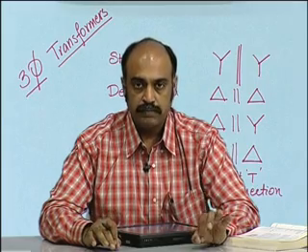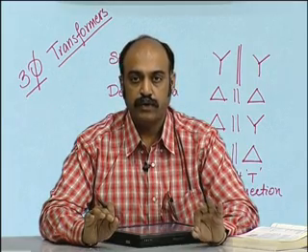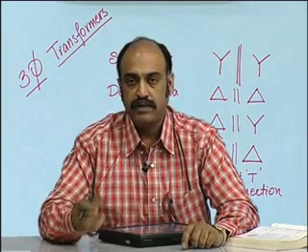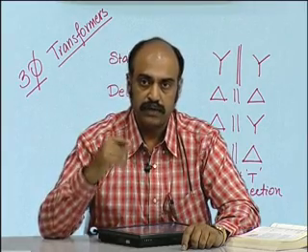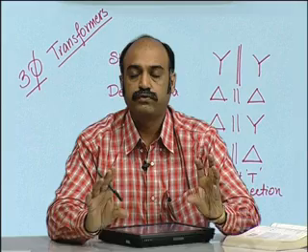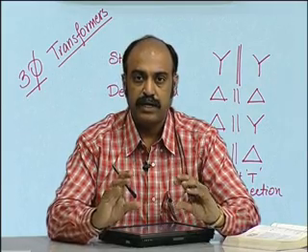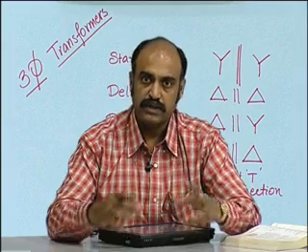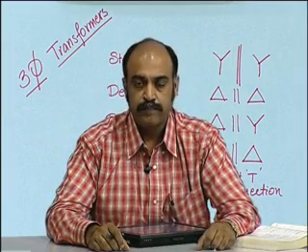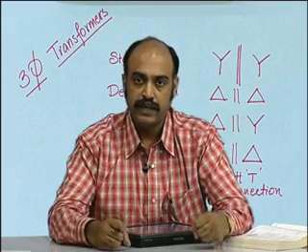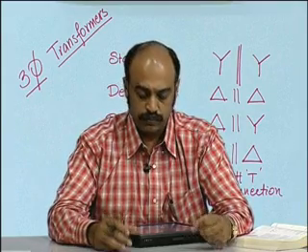It uses the same principle, that is Faraday's law of electromagnetism, which is the induced voltage is equal to N times d phi by dt, that is the flux which is there in the core. It is composed of three independent, separate single phase transformers connected in various topologies. These three single transformers are then combined into a single core.